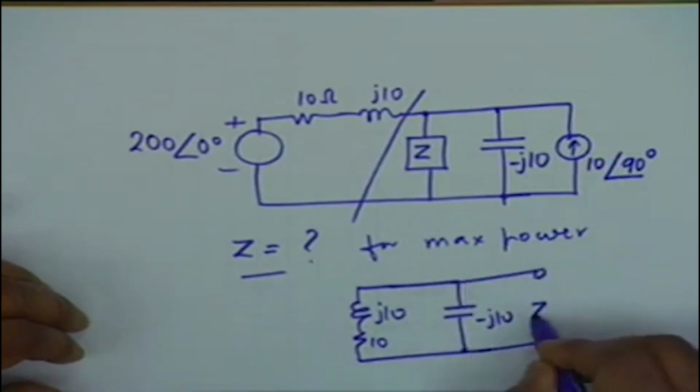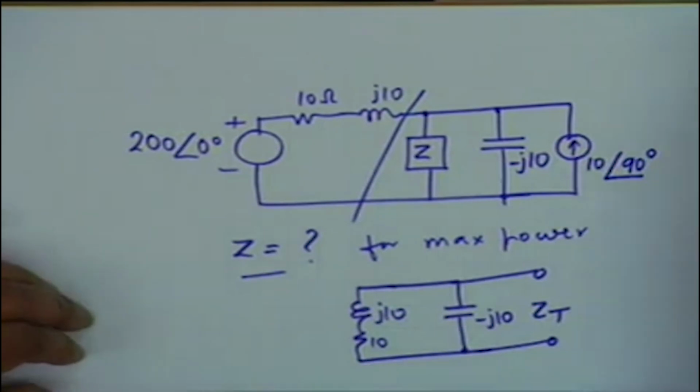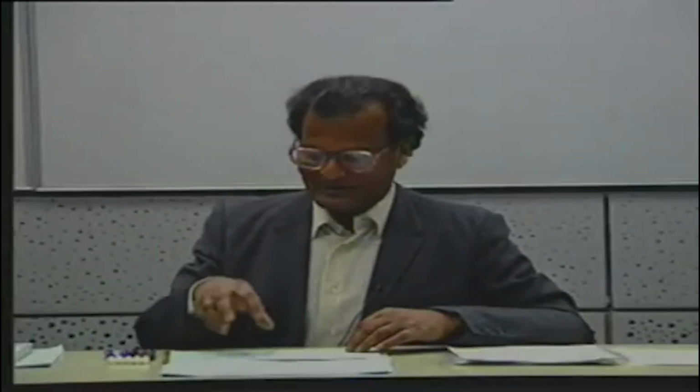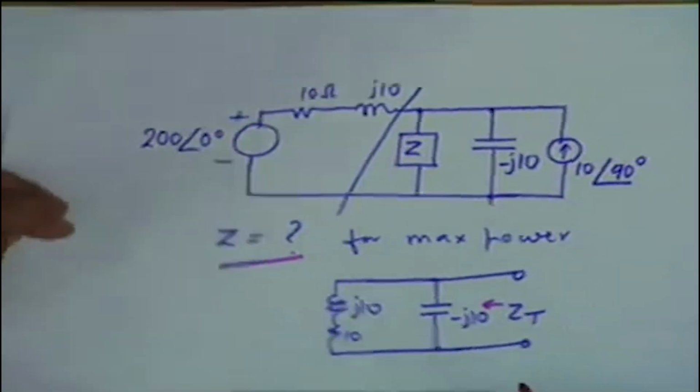That's all. Now if you think blindly, one can think while one closes his eyes, so thinking blindly is not an impossibility, but don't do so. Look at the problem carefully. You don't need to combine sources, because all that is asked is what should be the value of Z so that maximum power is absorbed. So you find out ZT.